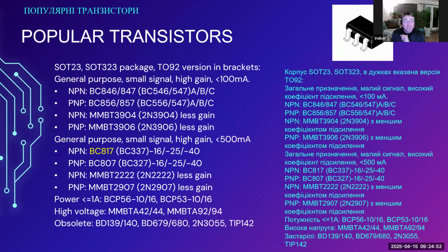They might be using the 2N3055. The 2N3055 used to be the standard power transistor. It is big. It is designed to be directly screwed onto a heatsink. It is basically a heatsink by itself, and it used to be very popular. So you might be seeing it in different applications and different schematics.